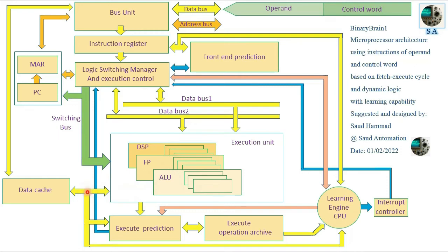Because two data buses are used, there is no need to store one of the values in a temporary register before performing the operation as usual. Instead, both values will be available at the input together. Same concept for the compare operation. The execution unit enables and connects the appropriate logic circuit for comparing the operands.